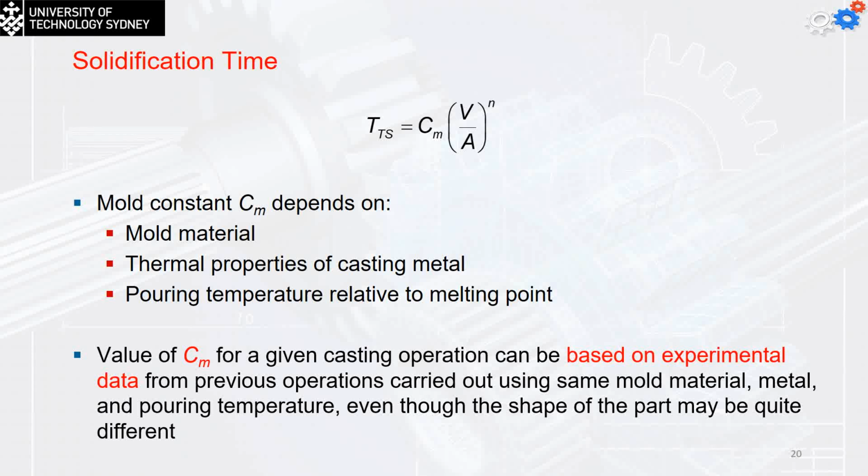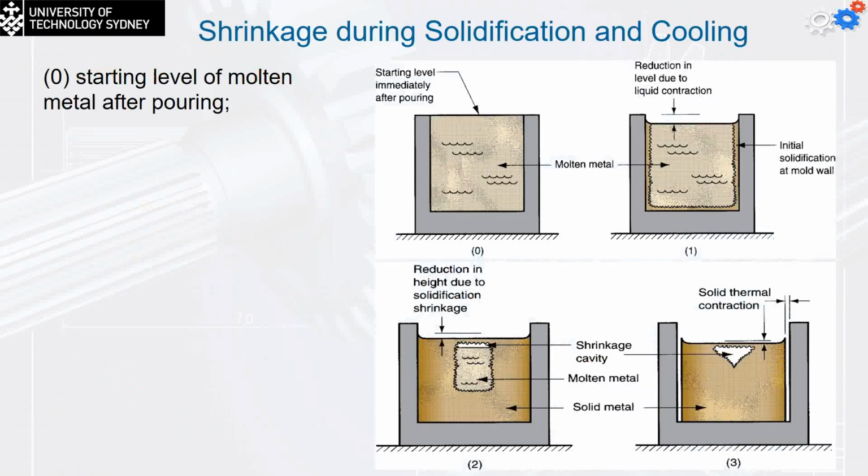Now, the main problem we have in casting is going to be the solidification and the cooling process. Now, we will repeat the same thing. If I start to fill the molten metal inside the cavity of the mold, we said that we are going to have a crust generated on the surrounding. It's going to chill, so delta T is too high, it's going to chill. The molten metal will remain in the middle.